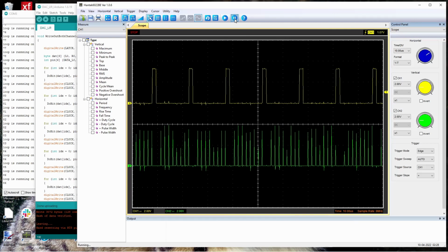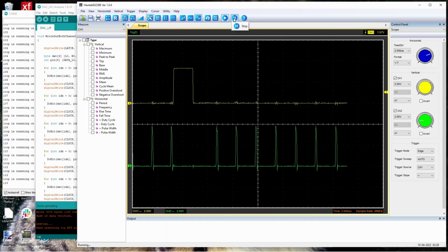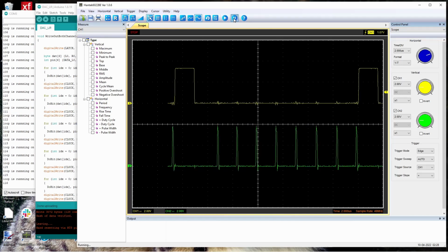So that's about what we would expect. You've got the latch goes low. Then you got 1, 2, 3, 4, 5, 6, 7, I think, 8 clocks. So that's working. Let me spread it out a little bit more. It's pretty good looking right there. Okay, so what do we have here? Because we have to take the time to set up 5 more data pins before we can fire the clock.